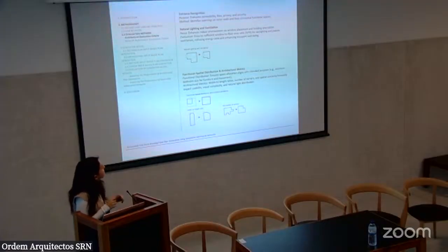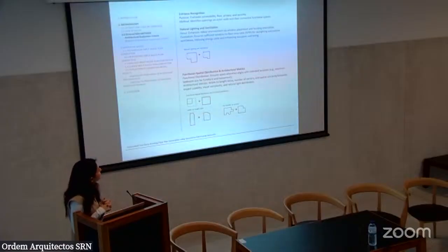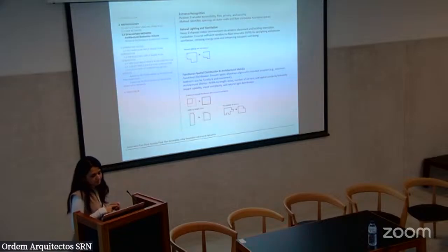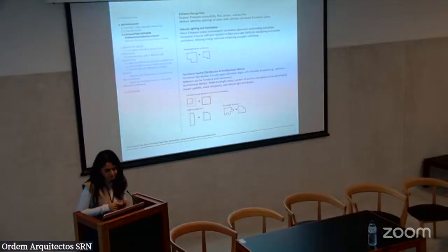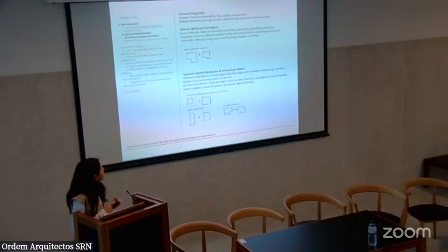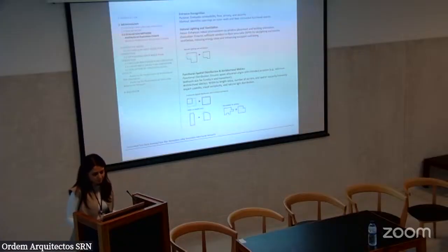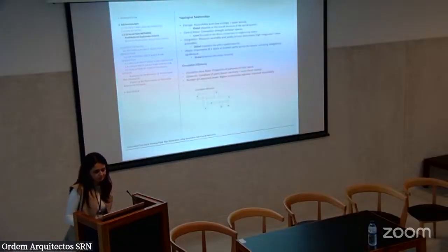The other one, window placement, is important in terms of energy cost, ventilation, and occupant well-being, and we calculated it with the window to floor area ratio. And the other one is more geometrical metrics: we check the spatial distribution, the area of the functions, window to wall length ratio, and number of corners, to check the visual complexity and the natural lighting distribution.